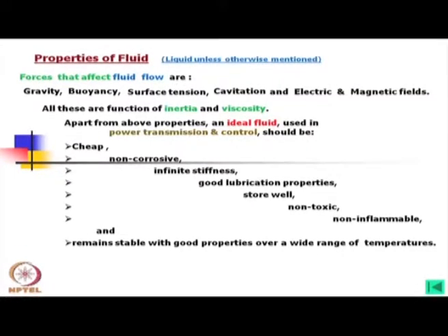Non-toxic. This is a great problem with fluid power, because when heat is generated, the oil vaporizes to some extent, and this gas is not good for health. However, it should not be very harmful and it should not be toxic. Most importantly, it should also be non-inflammable, because in many applications there is a possibility that it may catch fire.